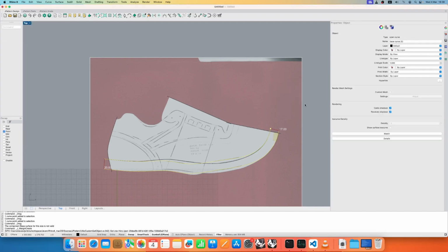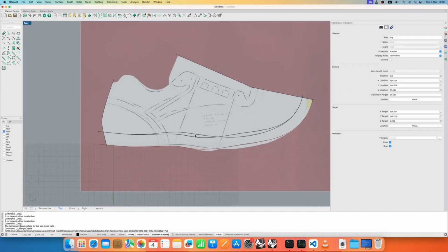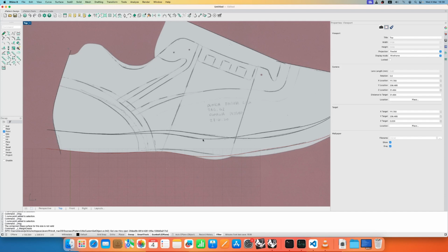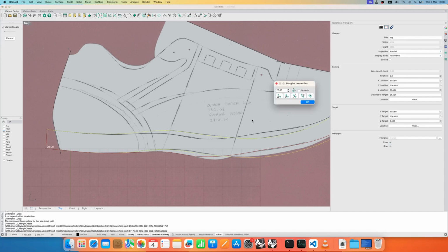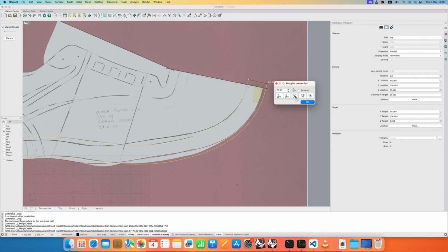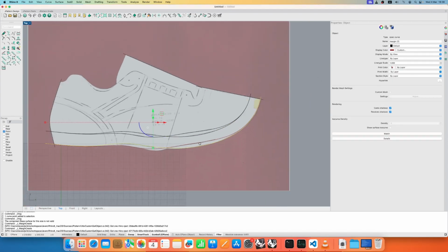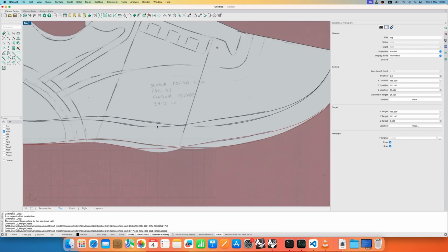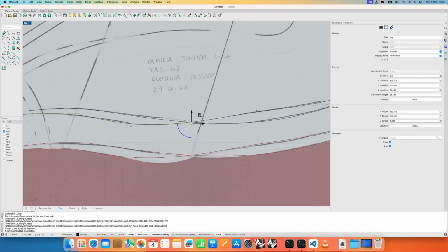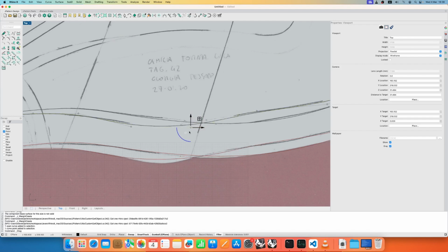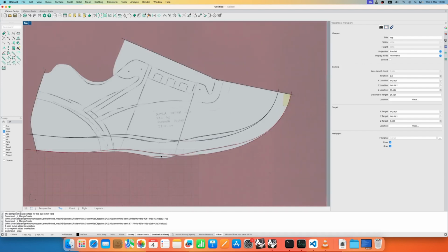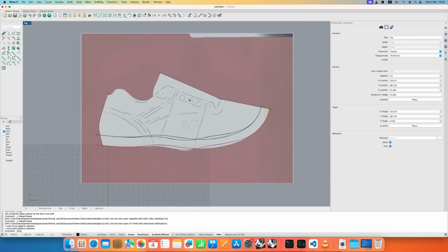So I created my margin here, and now I would like to do the same for the other curve. I can do that by clicking on my margin, selecting the other curve, doing the same thing. Here I select my offset point and go down to 17, and there I have it, and this is working. Maybe I need to fix this curve a little bit. It doesn't look that good. And you can see that everything adapts, which is nice, and it's a thing we can do.